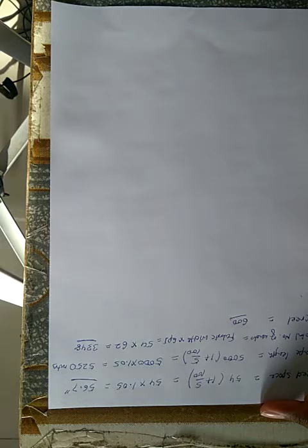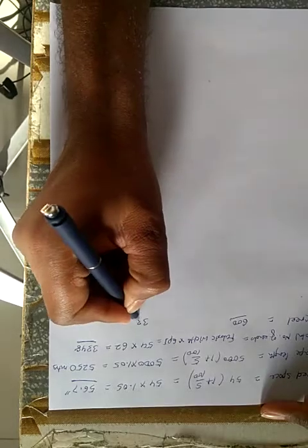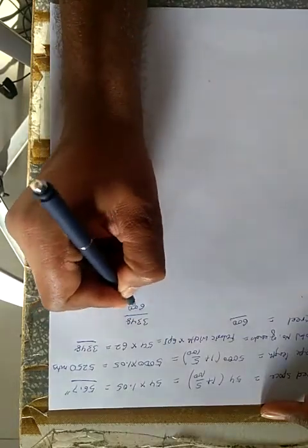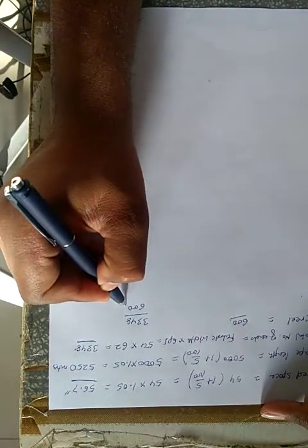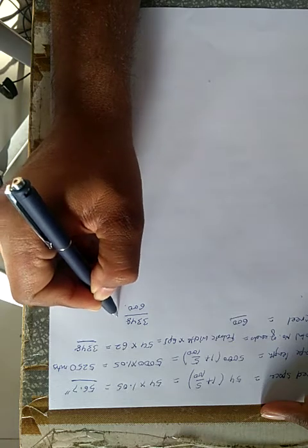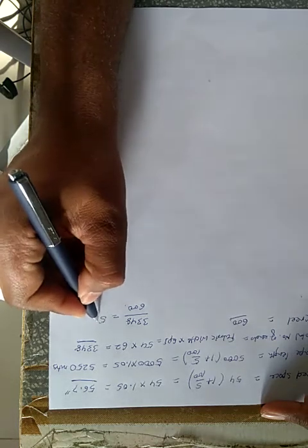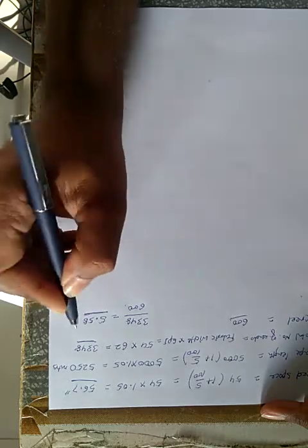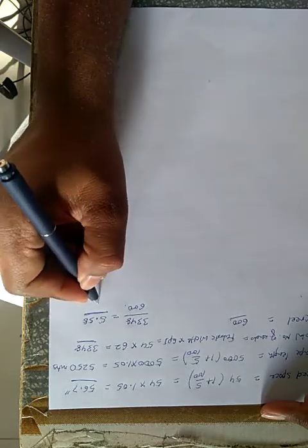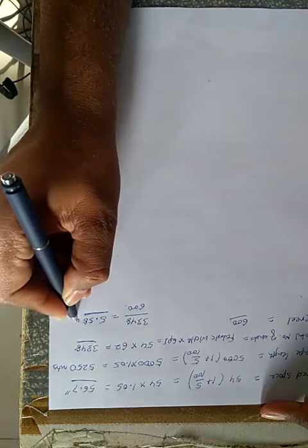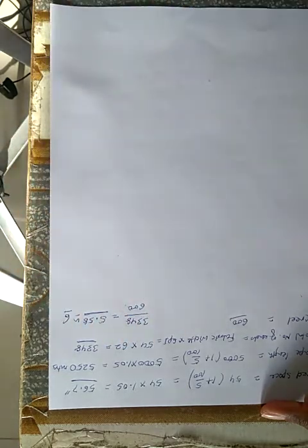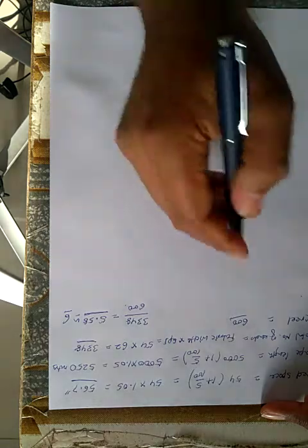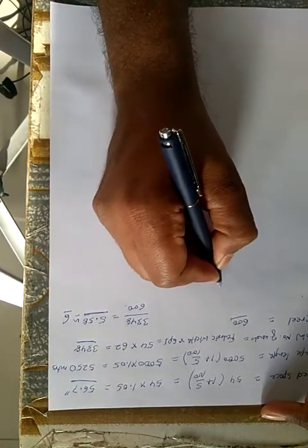So we have 3348. Now we will divide it by 600, which is our maximum creel capacity. This is the total number of ends and this is our creel capacity. This comes around 5.58. So approximately we have to produce 6 warper's beams.